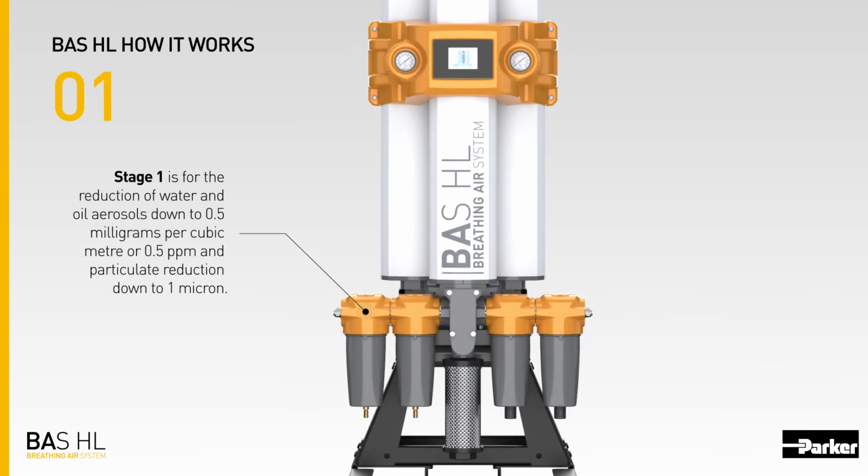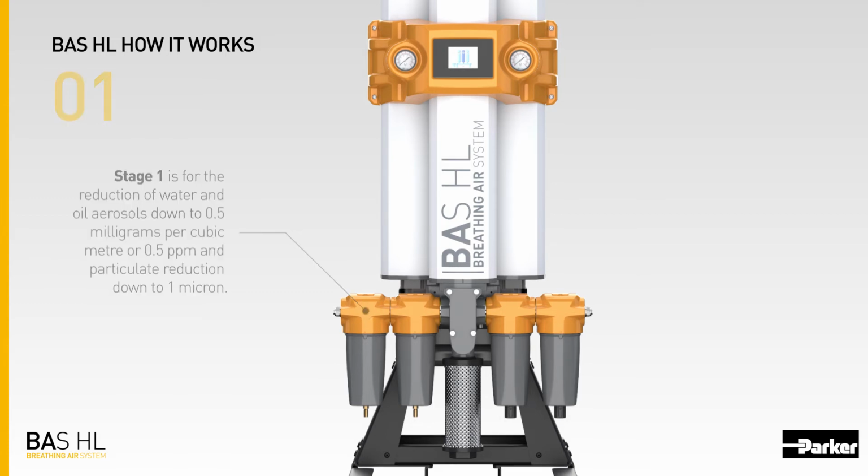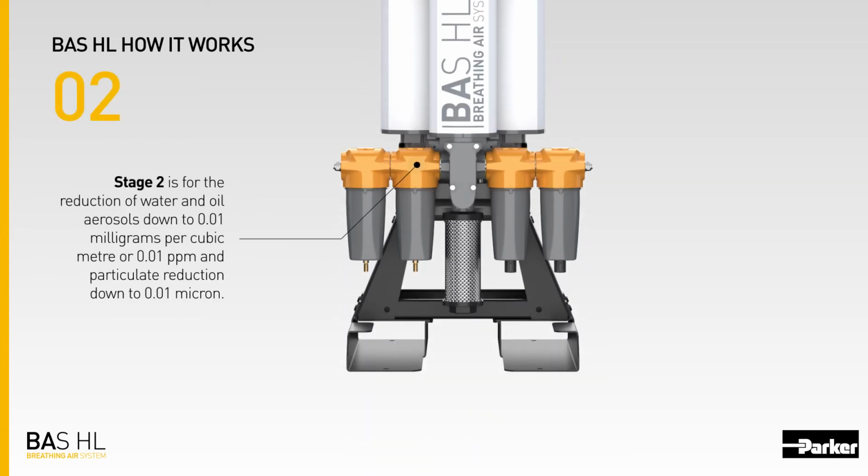Stage 1 is for the reduction of water and oil aerosols down to 0.5 milligrams per cubic meter, or 0.5 parts per million, and particulate reduction down to 1 micron. Stage 2 is for the reduction of water and oil aerosols down to 0.01 milligrams per cubic meter, or 0.01 parts per million, and particulate reduction down to 0.01 micron.